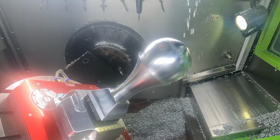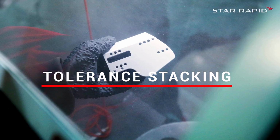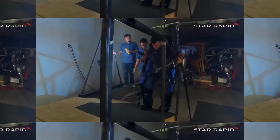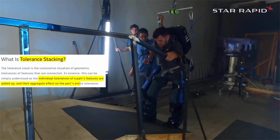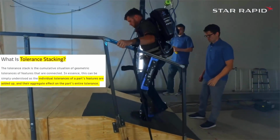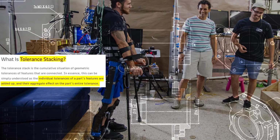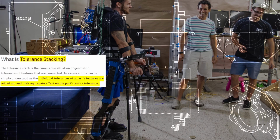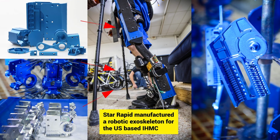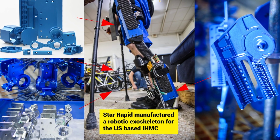There's one last concept we want to add before we explain how all this fits together, and that's the idea of tolerance stacking. For example, if you have a complex assembly with many parts, and all the parts need to fit together to perform a certain function, remember that each part will have a tolerance or deviation from the nominal. The more parts you have, the more tolerances can add up, little by little, stacking up. So there's the possibility the cumulative result of all these minor variations can be far off from the nominal. That's why it's essential to not only measure individual components, but also complete systems.